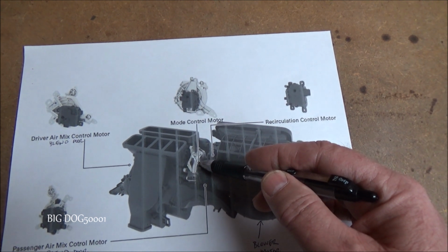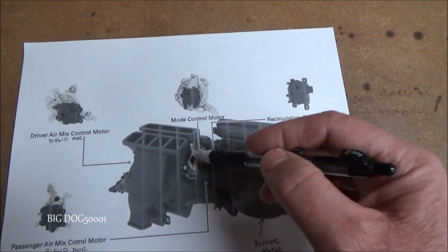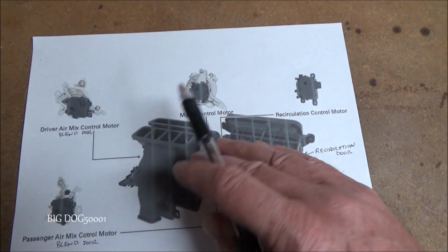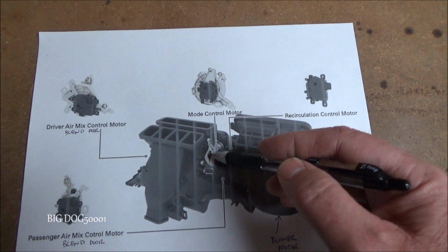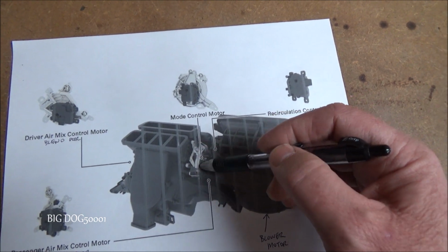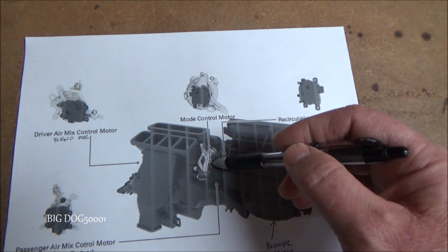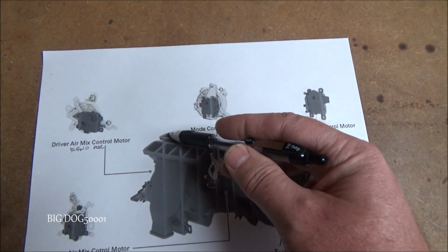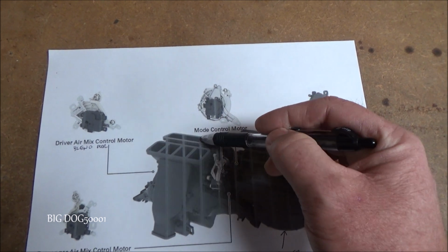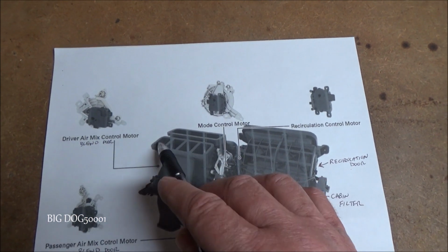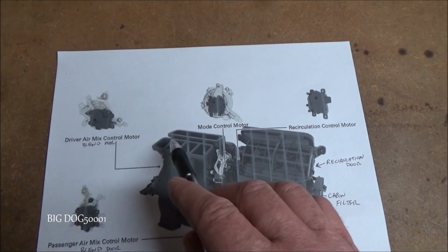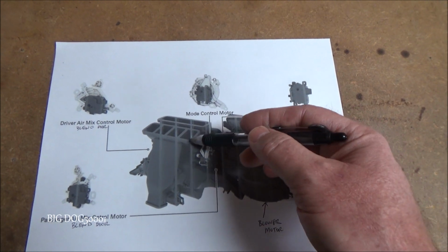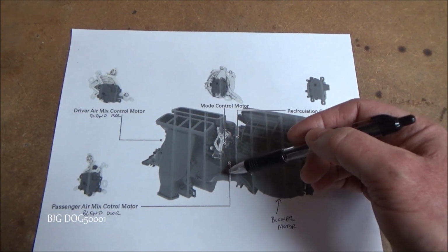Right here would be the mode control motor, and this one just has probably one rod, but some of these have multiple rods because usually there's a couple of doors that they're moving. So whenever you disconnect them, you might have one or two rods you have to disconnect also. On our mode control motor, it's going to change whether the air comes out up here on the defrost or right here in the vent. So that would be representative of the vents coming right at you, or going down to the floor. So pretty simple. It's just going to move the air back and forth, or a combination of them.